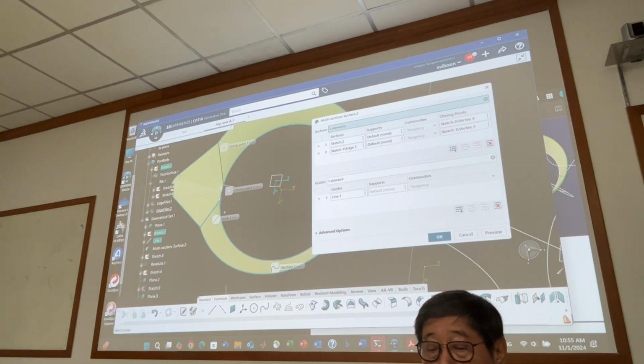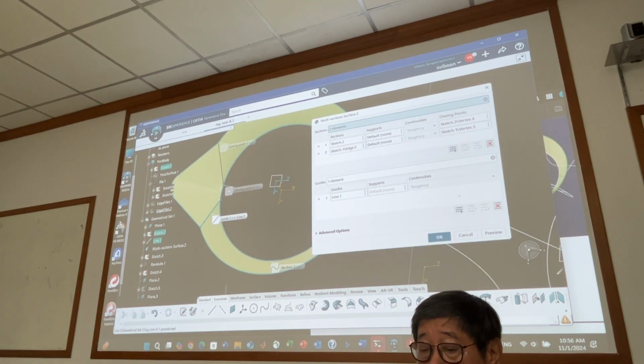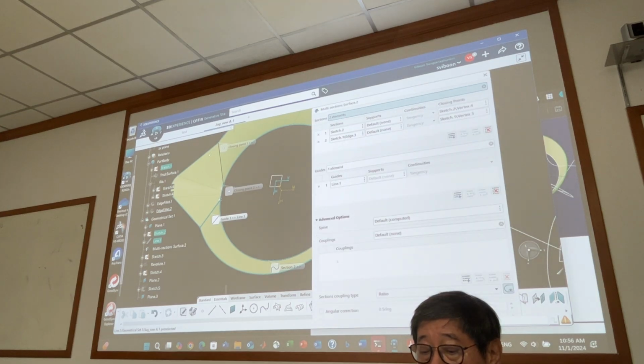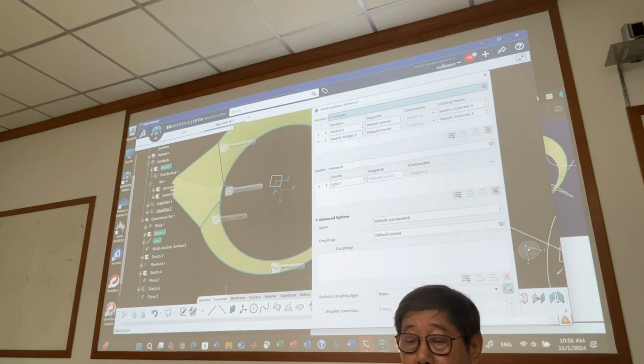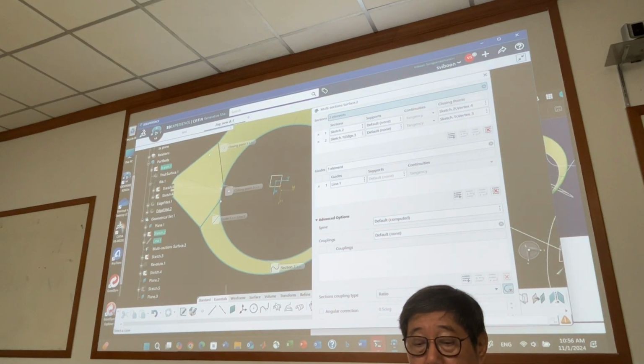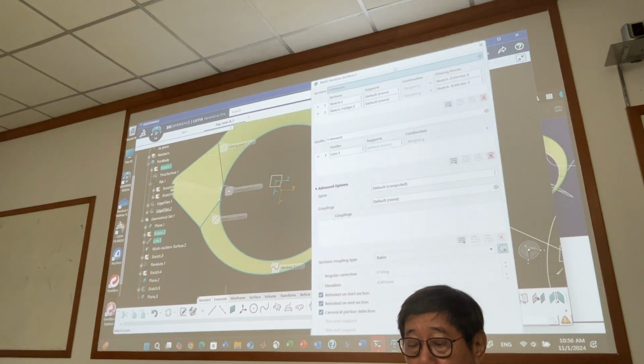If you have an explicit line here, you can use that line as a guide curve. If you don't have a line, that's okay, possible. You use coupling instead between this point and this point. Also possible. Same. You can use the line or the coupling, coupling point to point. This point you don't have to do, because it is automatic, because you are using a closing point. Here you just make a closing point here, coupling between this one, also okay. Either one can be done anyway.